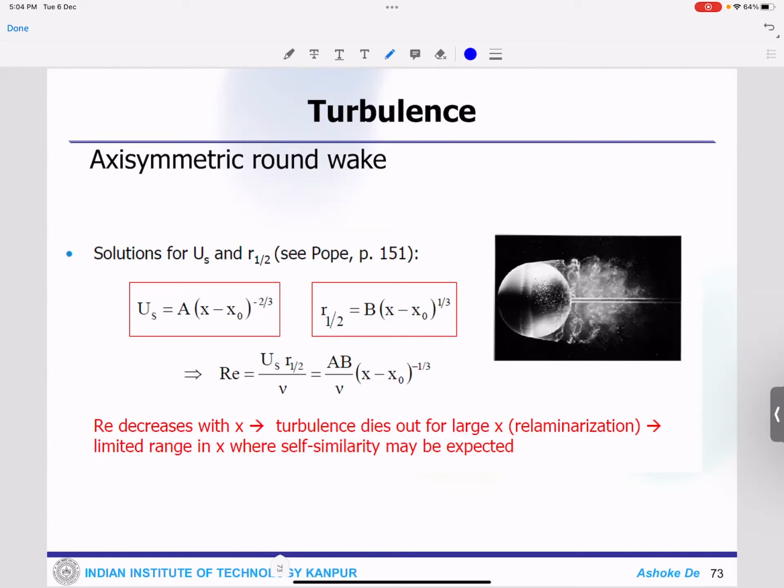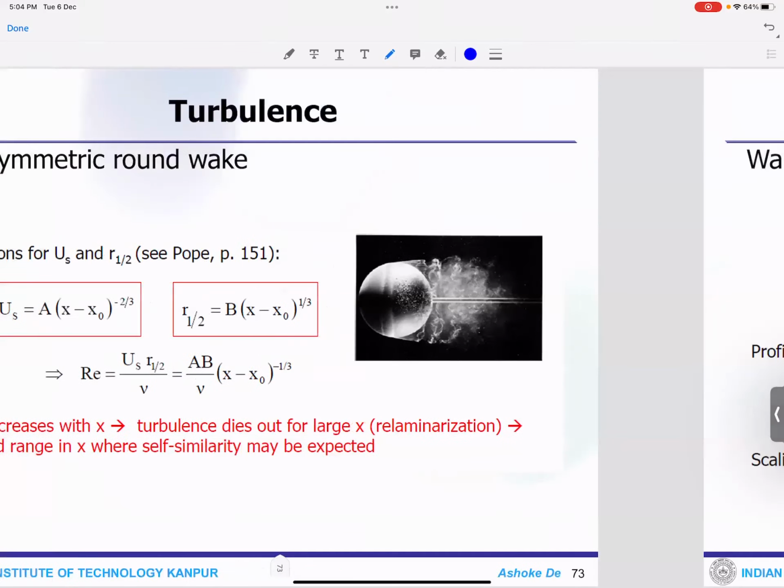So what it does exactly is the asymmetric wake which is created when the bowler bowls. The asymmetric wake actually creates a different kind of drag. Obviously lift comes from the rotation, so different kind of drag. So that's why the ball swings actually. So that's a classical example where you have this asymmetric round wake.